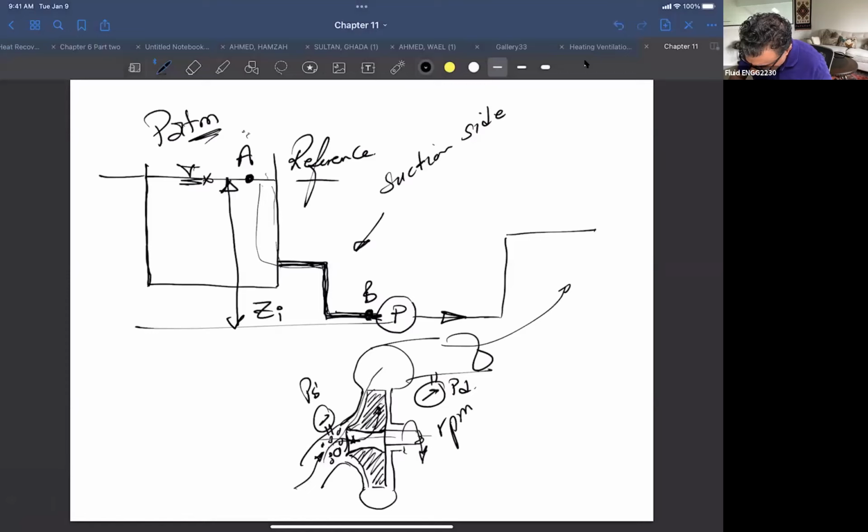This bubble will go in this direction, and what happens in this case? Those bubbles will see a pressure increase, and what will happen? All the vapor will condense, and the liquid will jump into the cavity of this bubble, where the bubble disappears. And if you remember in chapter 1, we talked about cavitation as a very serious issue that can happen in a centrifugal pump like that.